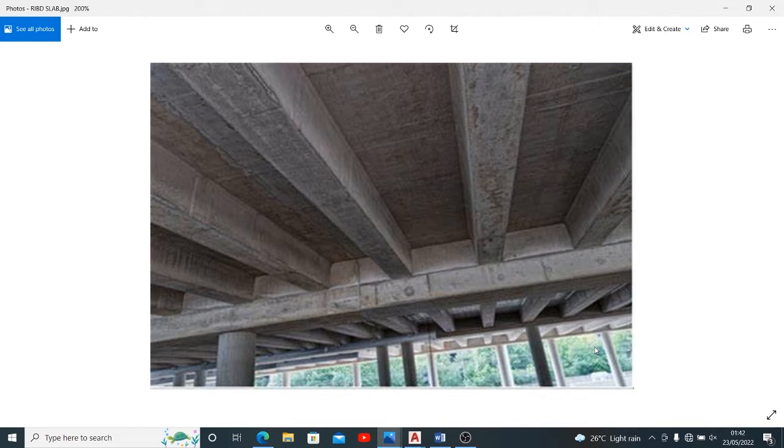Another advantage it has over solid slab is that solid slab, in its thickness and volume, constitutes a heavier load compared to a rib slab, where most of the time the thickness of the topping itself is a very light section, so it constitutes a relatively light load.